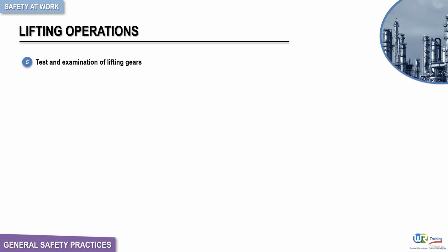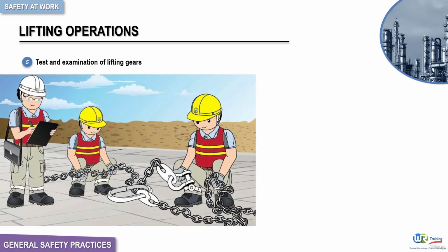The lifting gear should be tested and thoroughly examined by a competent examiner before use the first time, and then thoroughly examined every 6 months. The purpose is to ensure that the lifting gears are in good condition.